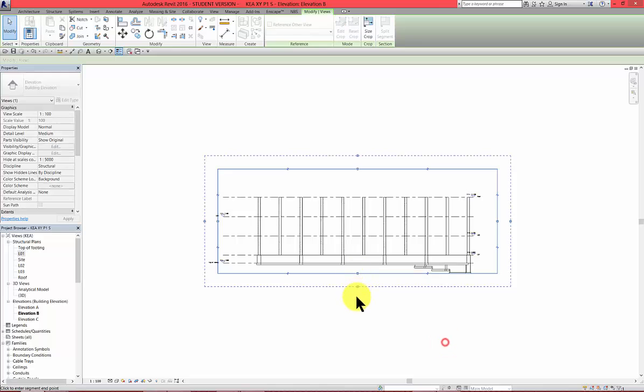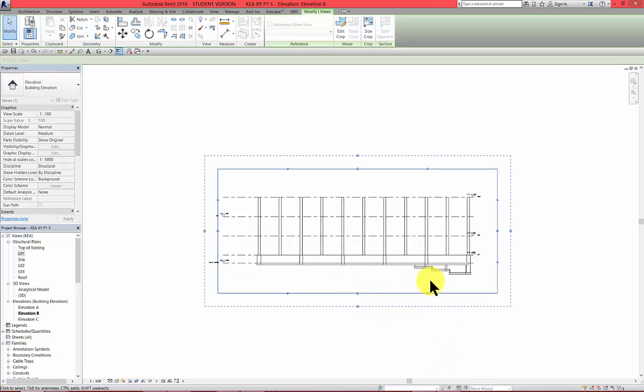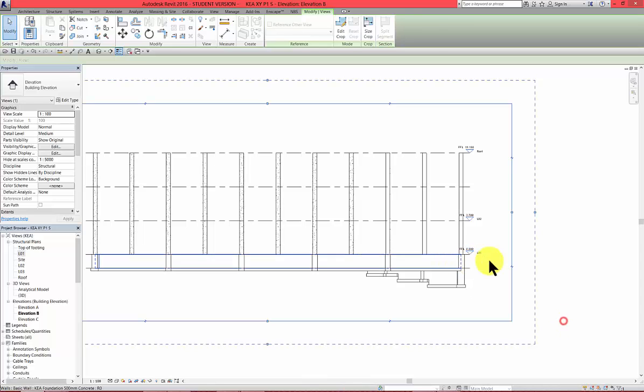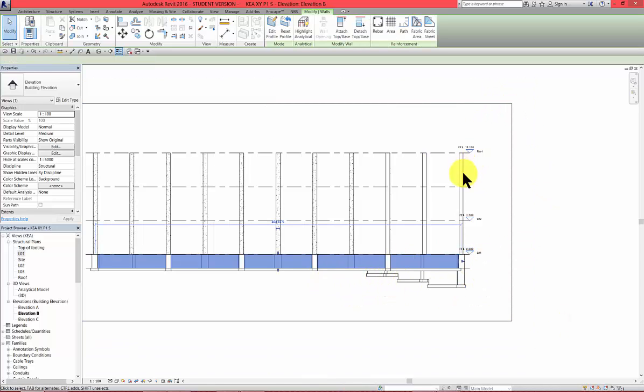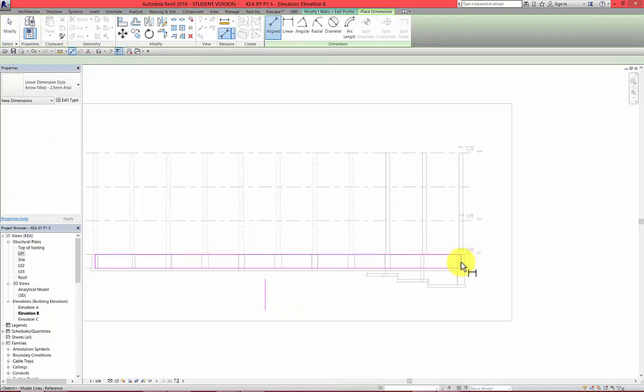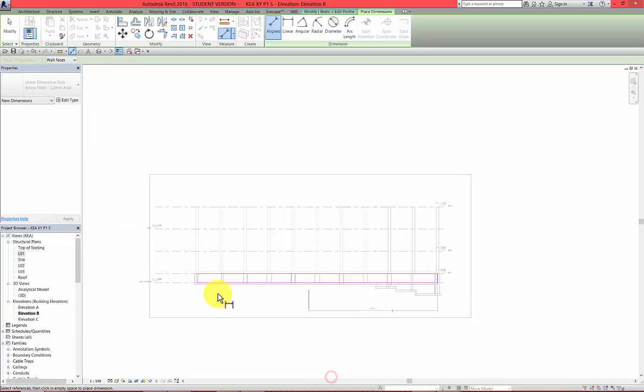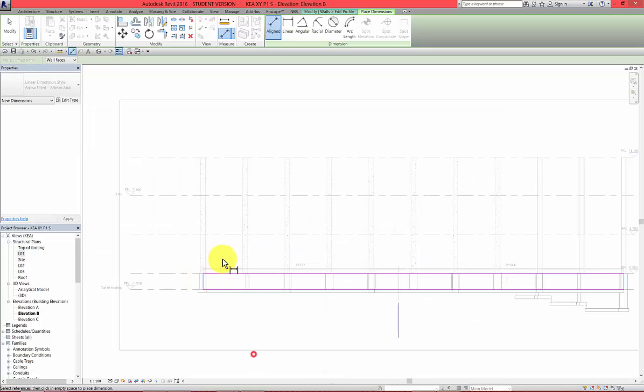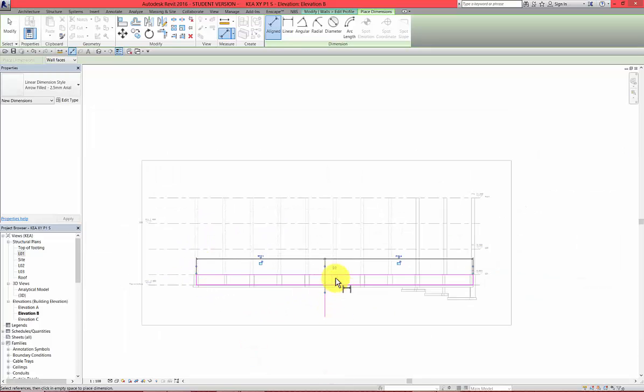I would like to get the crop view somewhere here so I can see what I'm doing. And now I'm ready to create the steps. Select the wall, edit profile, line, annotate a line, and we'd like to align this with the endings and then equal.